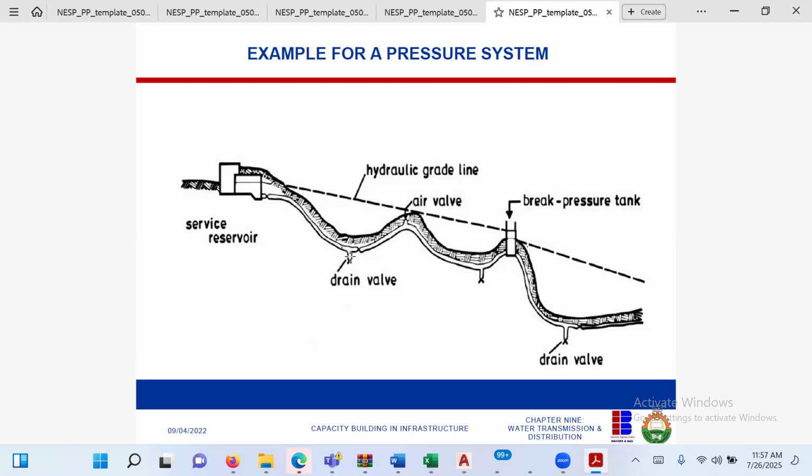Then the lower part, you need to have drain valves so that they will be releasing pressure, because if not, these places will break. I think they're having that problem in Abuja. The Abuja one is because of the kind of materials they use. The material they use is not PVC and is inelastic. So the pressure keeps breaking them at those inflation points.